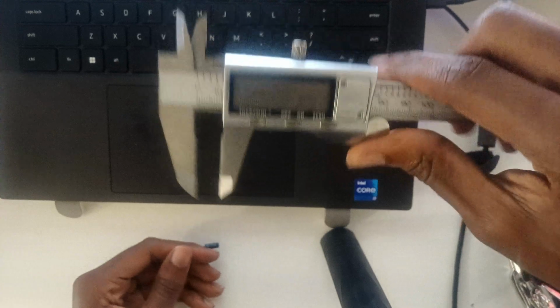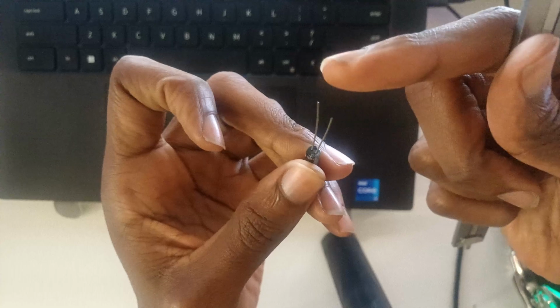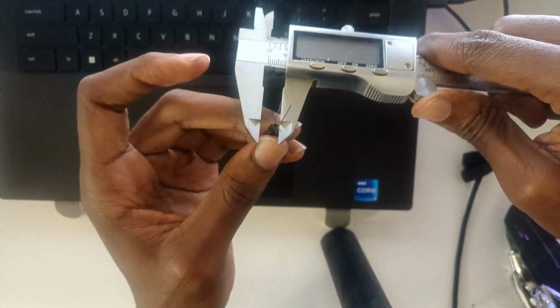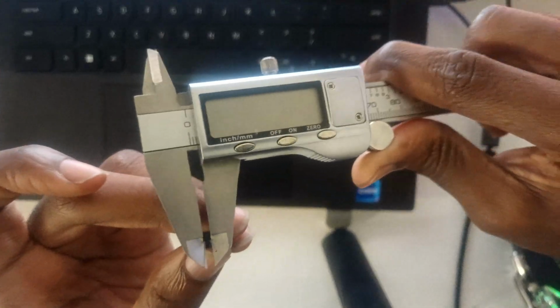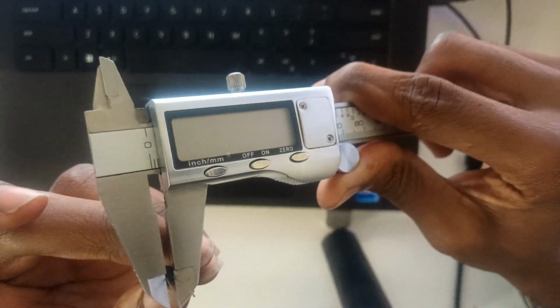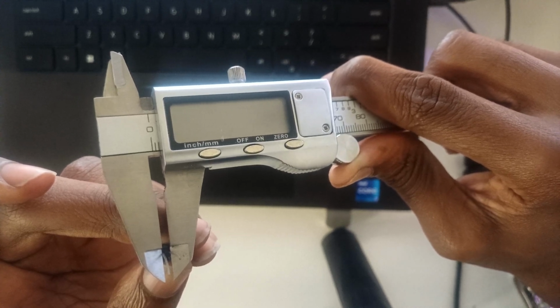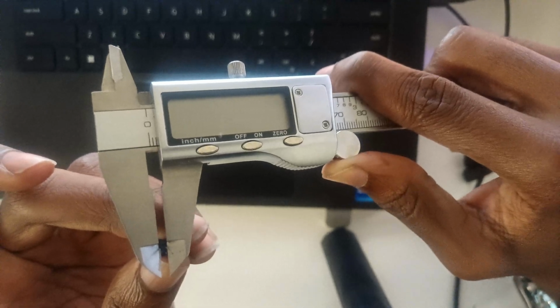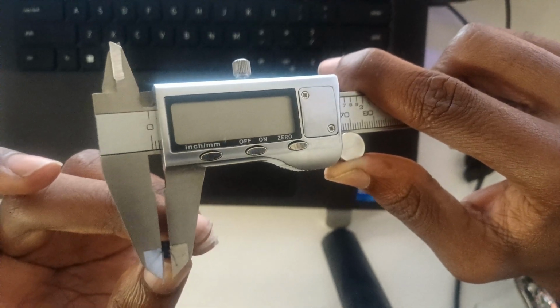One important tool for engineers is the vernier calipers. It helps measure distances. We want to measure the pitch of the two legs. I'm going to use the outer parts of the calipers to measure the pitch. And if you observe, we are getting 2 point something. I think it looks like 2.54 because 2.54 is quite a common value. It's not exactly on the 2, it's a little bit after the 2. So we'll look for something a little bit above 2.